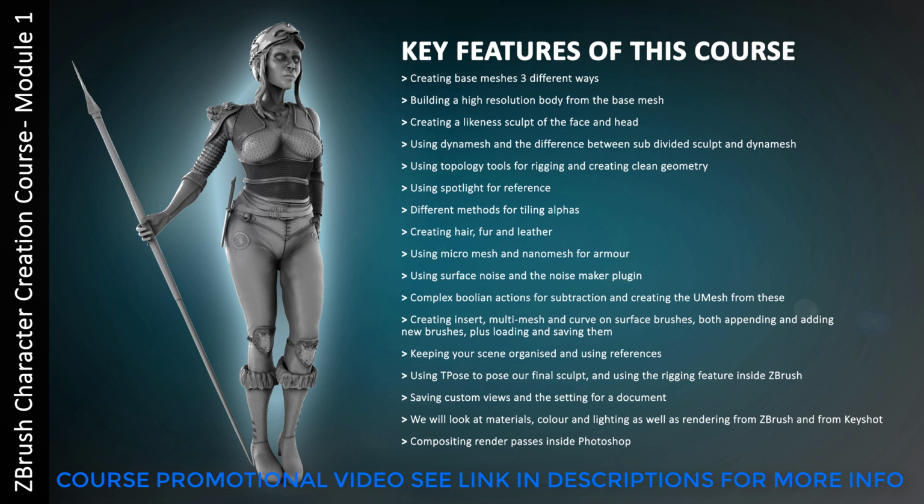We'll be creating a likeness sculpt of the face. We'll be using Dynamesh and the difference between subdivided sculpts and Dynamesh. I'll be showing you the concepts there. We'll be looking at topology tools for rigging and creating clean geometry, using Spotlight for reference and looking at reference in general and the importance of it. We'll be looking at different methods for tiling alphas and a full demonstration of those methods.